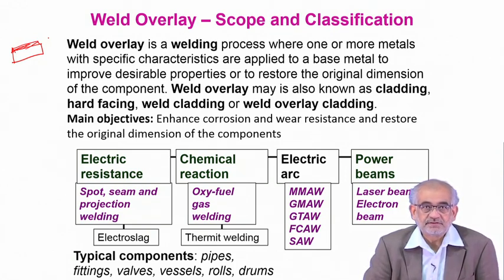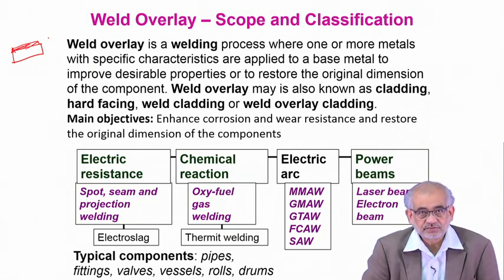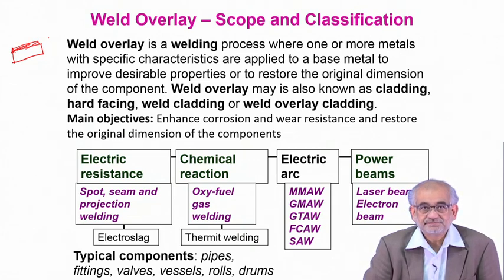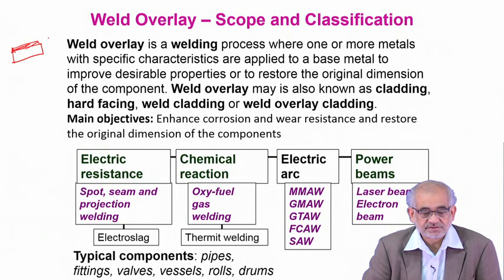So, we are not dependent on solid solubility, nor the diffusion coefficient. So, the thermodynamic or kinetic barriers do not play much of a role here. What is very important is that we should have a reasonable amount of interfacial bonding adherence. There should not be any big mismatch or spallation, and the coating also can be fairly thick.